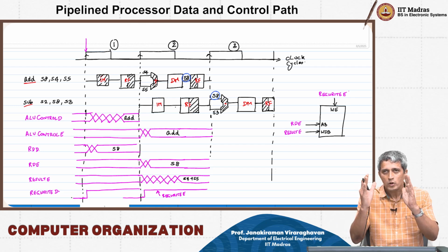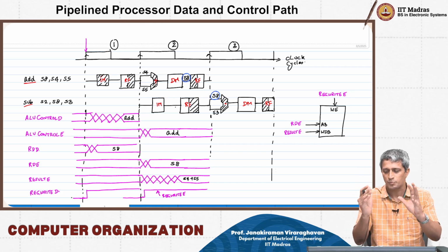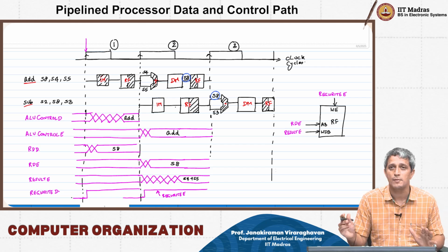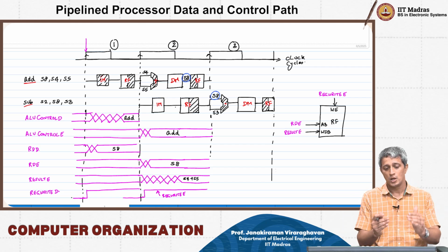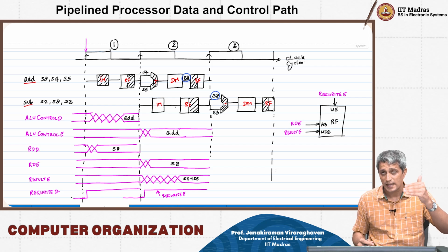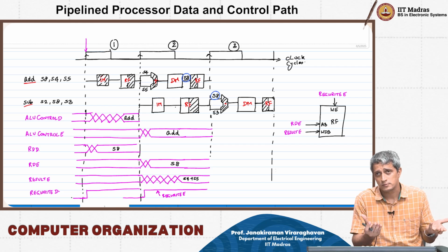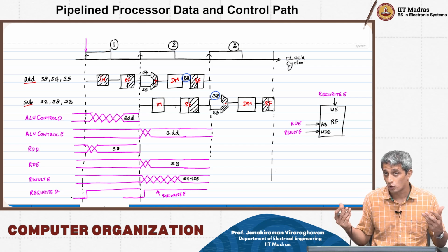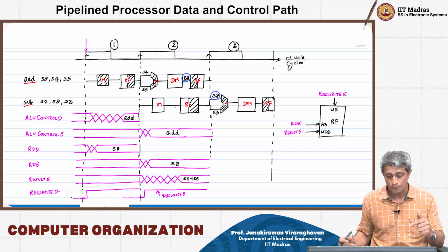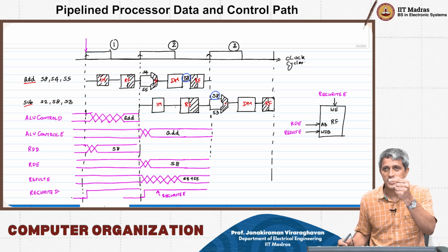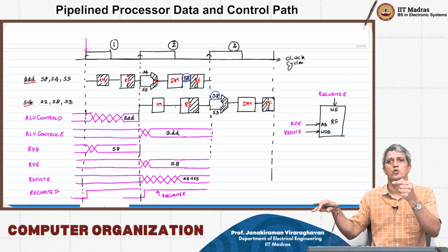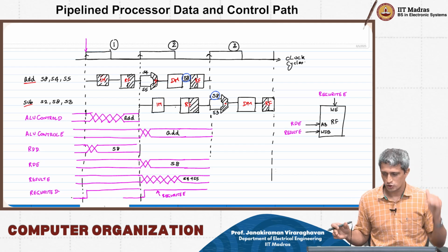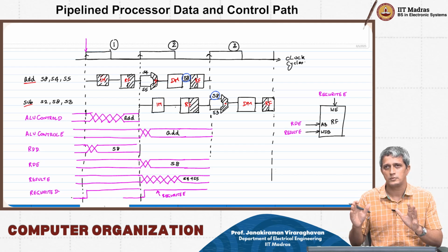Okay, so now if you look at the register file in this particular cycle here, these three signals have lined up very nicely. Remember that the next instruction could be something else. It could be a load word where there is no register write. If there is no register write, then what will happen? This reg write D signal in that phase will simply go down to 0, right? And likewise all this will happen. So that's exactly what is going to take place here.